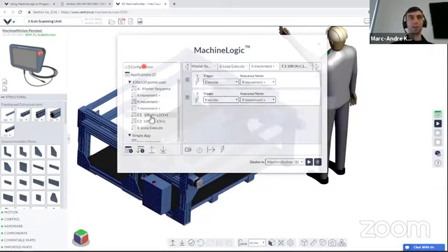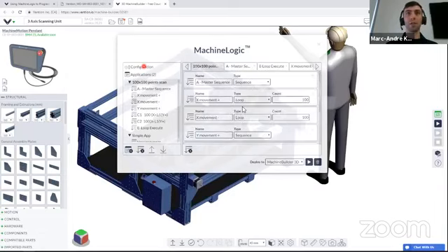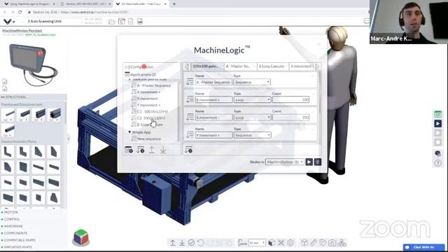All right, going back here, it executes both movements, and the X plus is really simple: it moves by 5 millimeters, again going back to the spacing that I had, and the same goes for the Y-axis since we have a square grid. So there you have it. It really calls one another, and with the right count of loops here, it will make a sort of zigzag pattern, making one row at a time, going up, 100 times in each direction, covering the whole spectrum of holes, which was 10,000. So great.